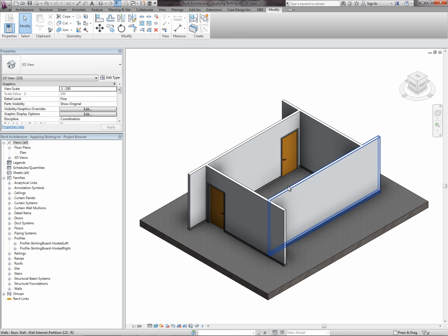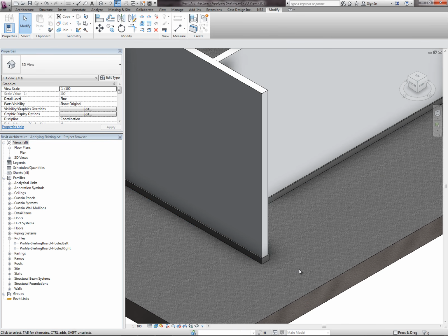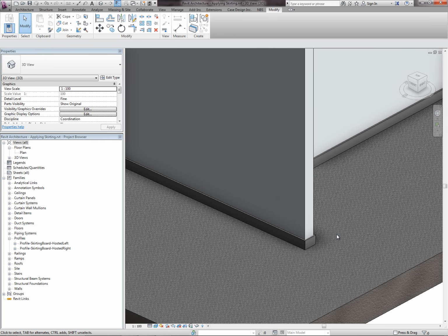Now the reason for doing this is slightly complex. Revit reads profiles differently whether they are used as a sweep for a finish or a reveal for a recess. At present, this partition has a skirting that was created using a profile with the lines orientated to the right. Now we can move this skirting back into the partition using a negative offset, which I'll show you now.